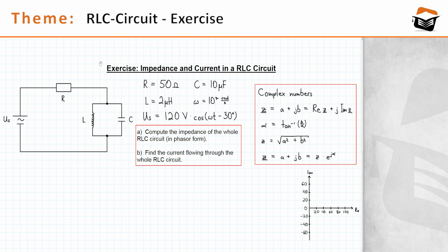As I said before, we will be using complex numbers to compute the impedance of the circuit as well as the parallel subcircuit, because if you have a capacitor or an inductor or both, you have a phase shift that occurs when you apply a voltage and then you measure the current. And to take the phase shift into account, it is convenient to use complex numbers.